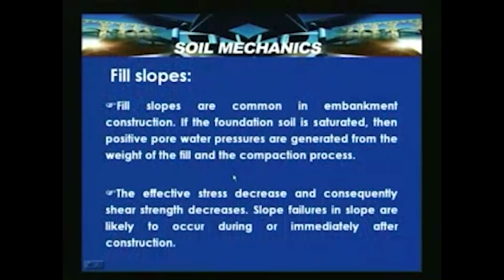And fill slopes are common in embankment construction. If the foundation soil is saturated, then positive pore water pressures are generated from the weight of the fill and the compaction process. Because of the weight of the fill and the compaction process, positive pore water pressures are generated. So, the effective stress decreases and consequently the shear strength decreases. Slope failures in fill slopes are likely to occur during or immediately after construction.